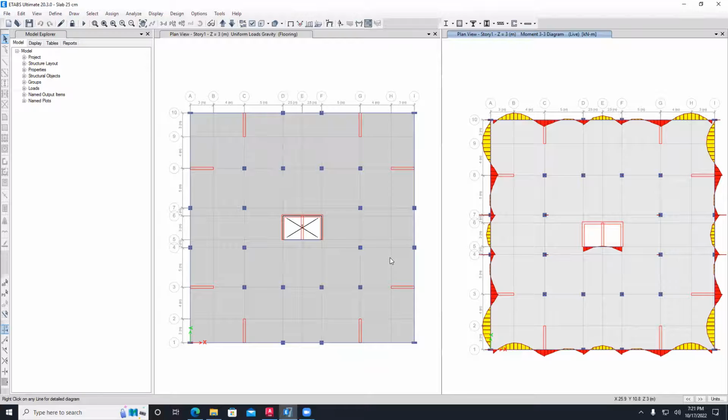So you guys know there's a column here and a wall here, right? The column is like a hinge, like a support. And the wall is also like a hinge because it makes supports like this. So you can see the moment going positive, negative at the column, positive, negative, positive, negative at the column. But if this column is a hinge and there is nothing else, the moment is supposed to be near zero, right? Why is it not zero? There is some moment.